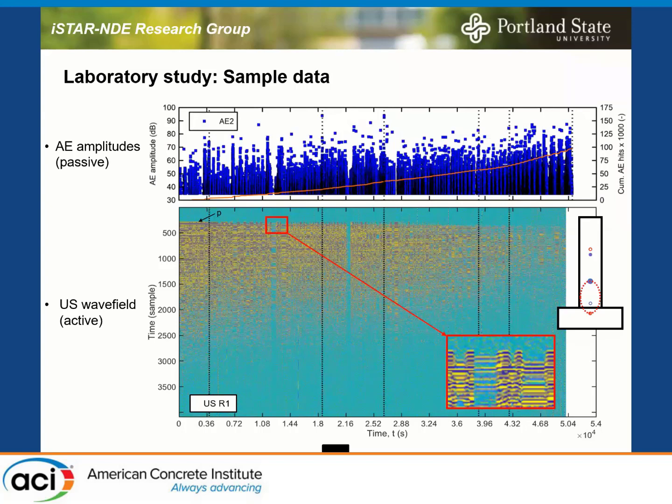If I take a column where I put them in when I cast them, and I do the same column where I drill them in, and I compare the data, it will look a little bit different. But that actually doesn't matter, because what I'm looking for is relative changes between the signals. I'm not looking for an absolute waveform shape. I don't care about that. I care about consistency between measurements. So if that signal looks a little bit different compared to another setup, it doesn't matter. I'm looking for changes between signals. That's another advantage of this.